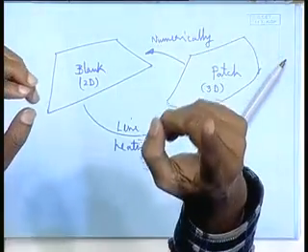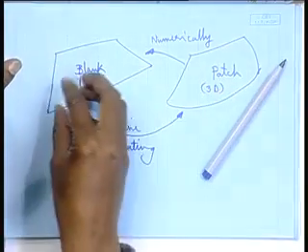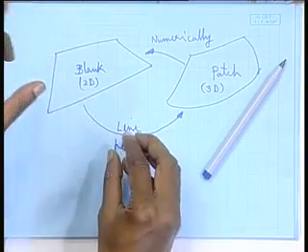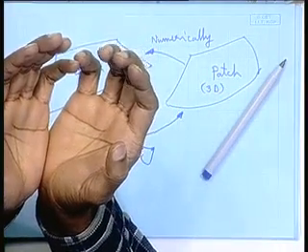If I can find out the distribution of the strain, then I know how to generate that strain distribution. I will find out the principal strains, the lines of the principal strains, right. Wherever you have the maximum strain, a line perpendicular to that will be the heating line, because when I heat it, it bends perpendicular to that.